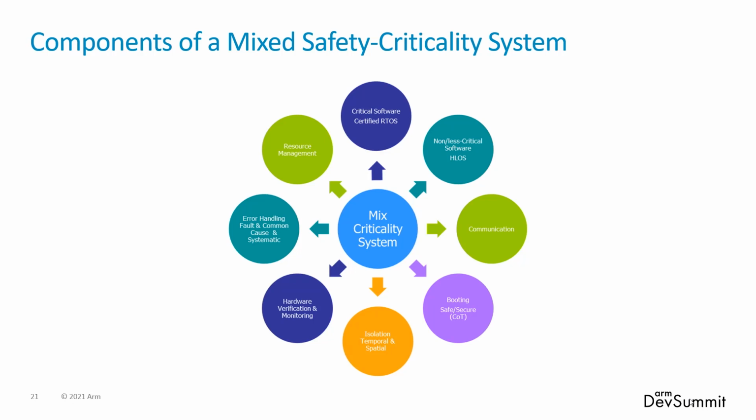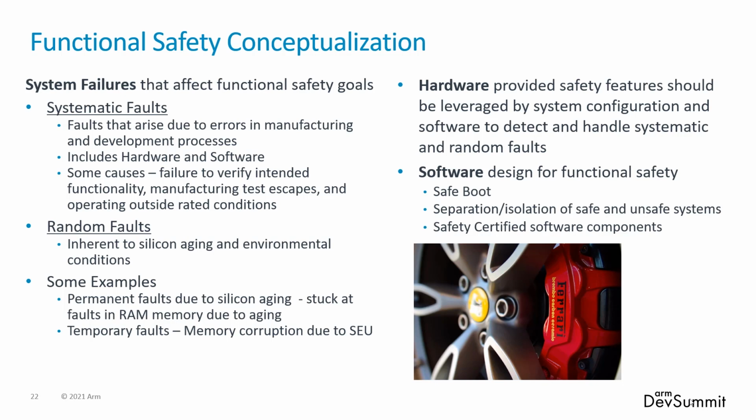Booting: do I have a secure or safe boot requirement? More than likely, yes, if I have functional safety. Obviously, we have to worry about isolation, not only from a hardware standpoint but from a software standpoint. And then there's the whole hardware and verification monitoring side of things, error handling and fault and common cause type stuff, and then resource management. All of these things come into play to really make up a mixed criticality system. And when we also talk about functional safety concepts, then we're talking about the different faults, be it systematic, random, things along those lines.